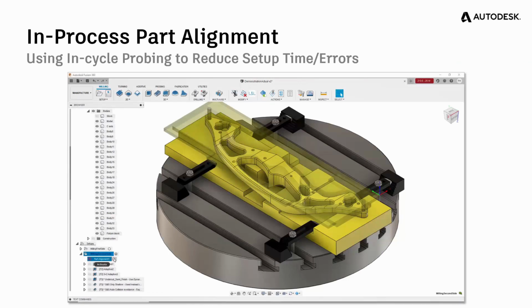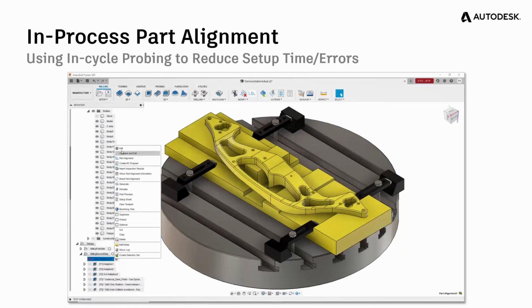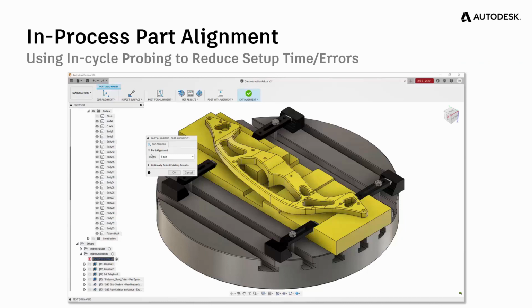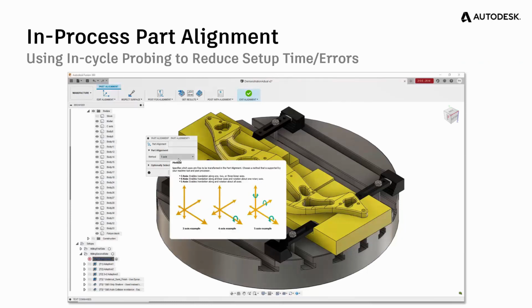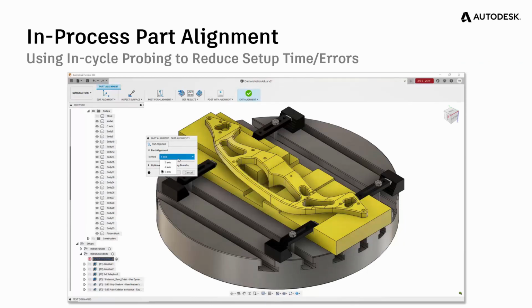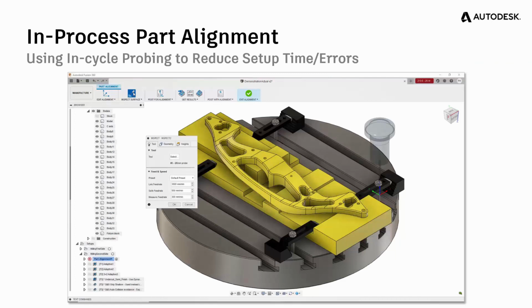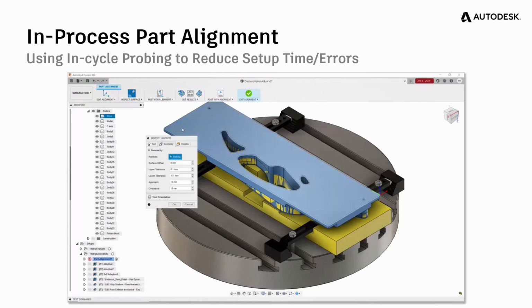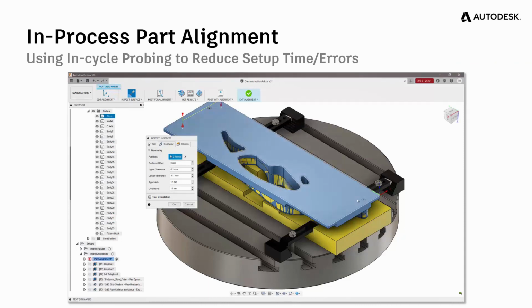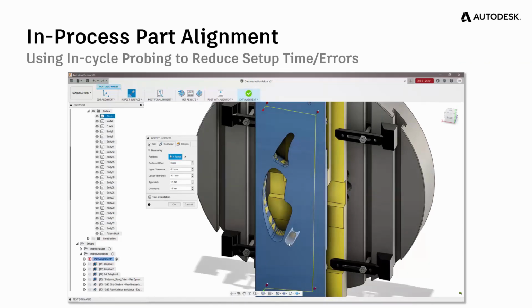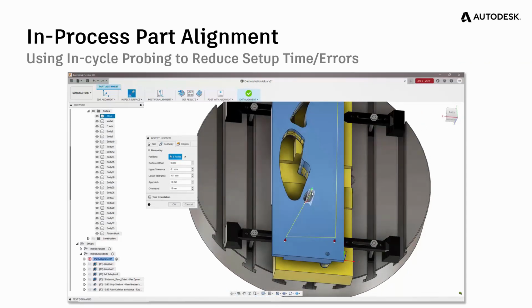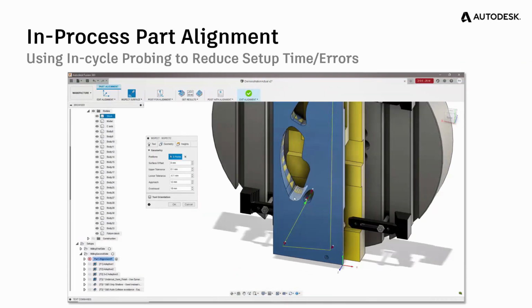We've also introduced the ability to create probe assemblies and surface inspection routines into Fusion 360. This is something we did last year, but the team has been working to take that one stage further. Now, this video shows expanding the functionality to support part alignment during machining setup. So here we can see a part alignment being defined and then a series of points being tagged for probing purposes. Here, we've chosen to measure against the machine stock from the previous machining operation.